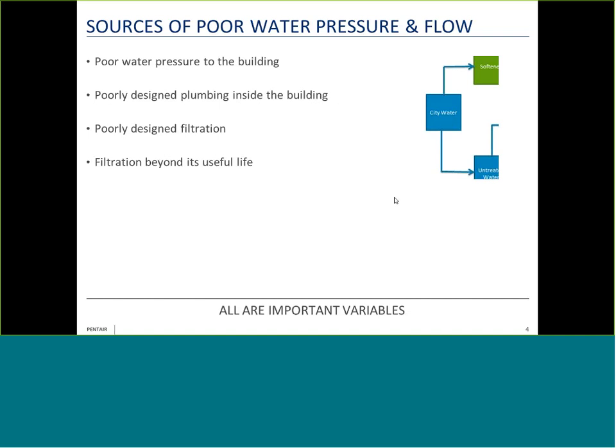than it can actually handle, causing premature fouling, or in some cases, pulling that dirt through that filter and causing chlorine breakthrough and taste or odor control breakthrough before what we need. Plus, now that filter becomes a restriction to flow rather than a smooth pathway if it's slightly undersized and not sized for peak flow rate.